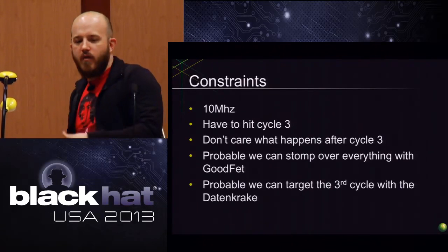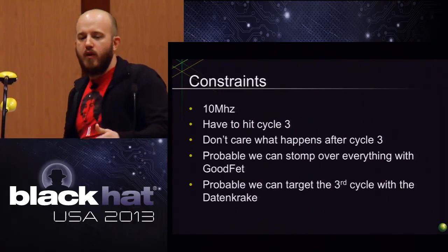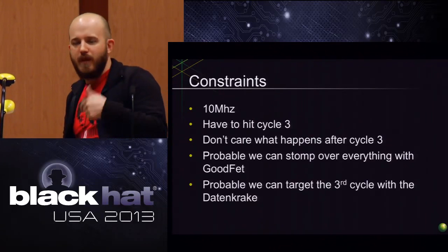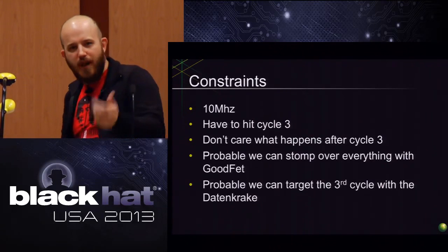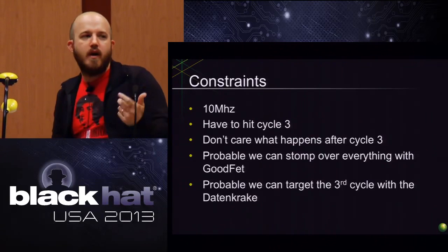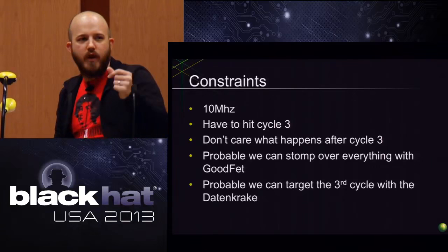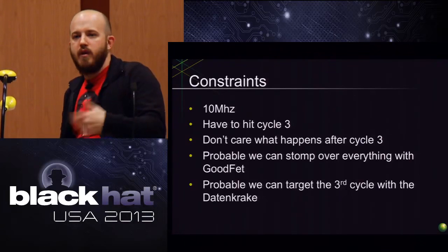So as long as the thing doesn't constantly go into a reboot loop, for example, and if you can get past that and keep it alive long enough to let the debug interface be up, then you'd be able to halt execution, and at that point, you've got the debug interface.